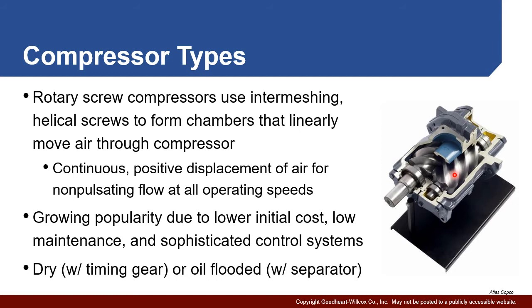A couple different styles we have are the dry and the oil flooded. Dry essentially uses a gear built into it to provide the timing to make sure that the two screw elements mesh together. We also can have oil flooded. Oil flooded actually puts oil in there and one of the screw mechanisms drives the other one, but with the oil flood you need to have a built-in oil separator before the fluid goes out to the system, because you're putting too much oil down the system. So it's required to separate that oil out.